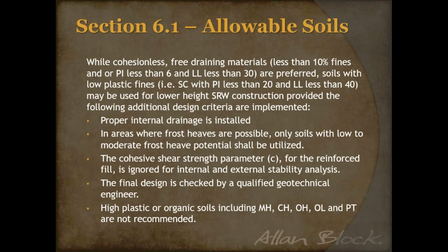Little note on allowable soils, we talk about cohesion. Cohesion is that soil property about basically how well everything kind of binds together. I always kind of remind everybody that cohesion is water soluble. So in our industry, we tend to ignore cohesion, whether that's for external and internal analysis. We do see cohesion jumping in on your bearing capacity calculations.